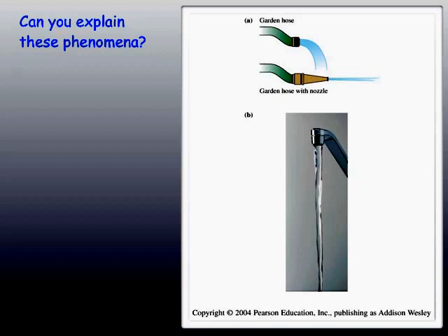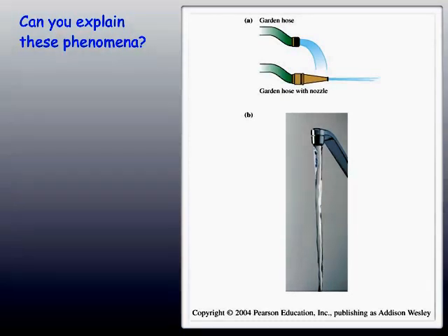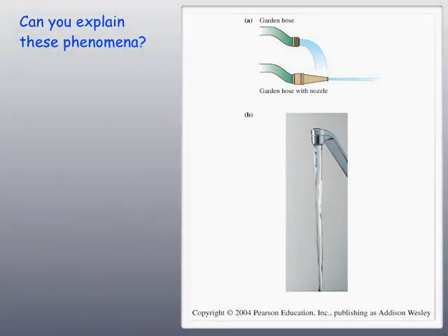When fluid gains speed, not only is it going through a smaller opening to gain speed, but if the fluid column itself is gaining speed, then the column shrinks in cross-sectional area. It can also start rotating and twisting in some cases. That would be an example of the rotational kinetic energy also coming into play.